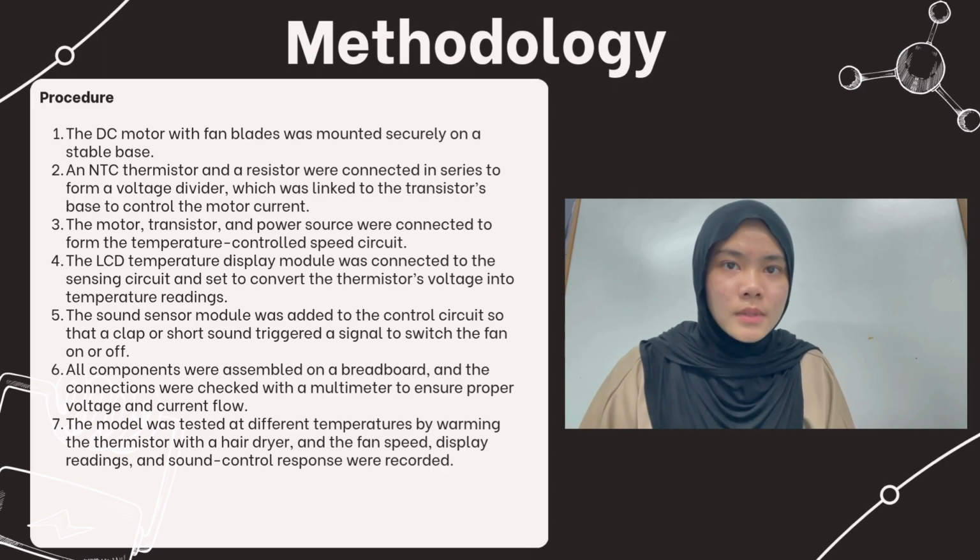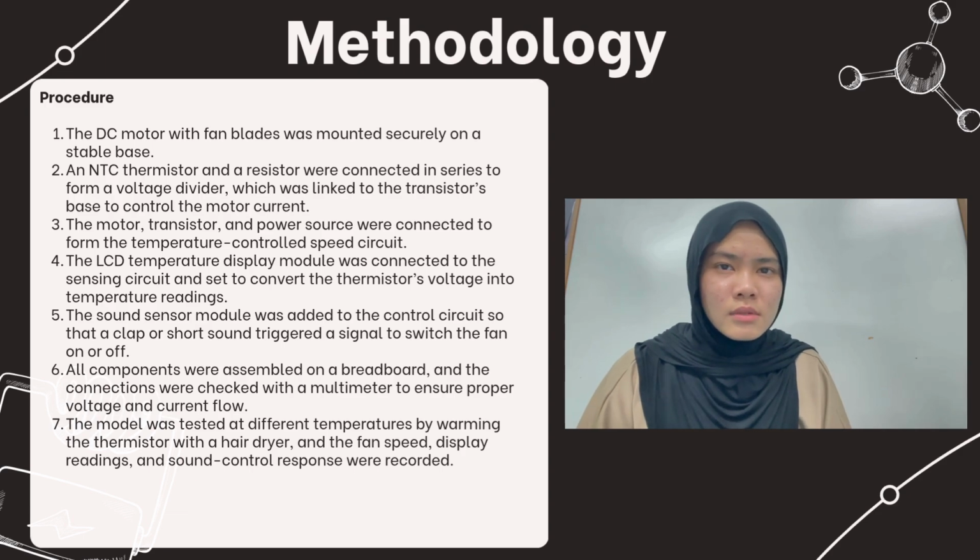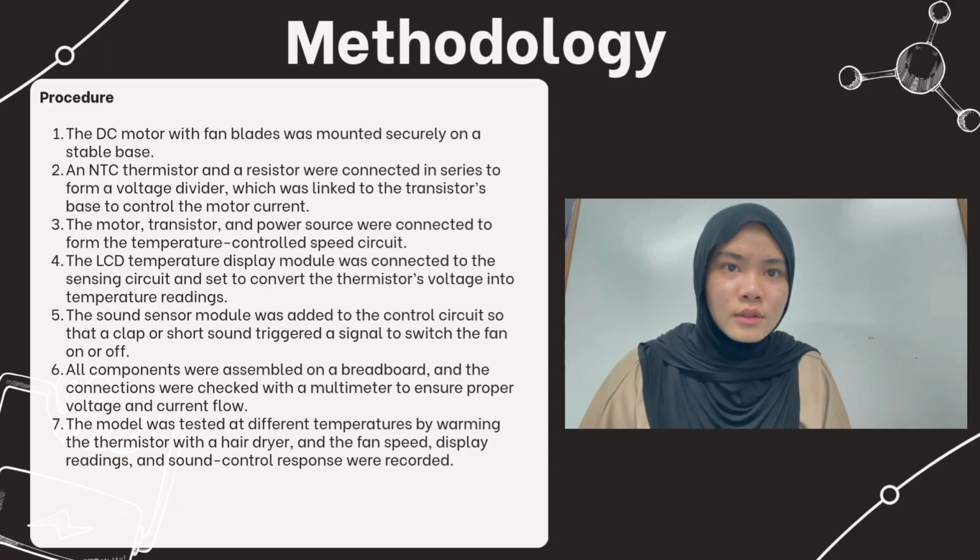The LCD temperature display module was connected to the sensing circuit and set to convert the thermistor voltage into temperature readings. The sound sensor module was added to the control circuit so that a clap or short sound triggered a signal to switch the fan on or off.